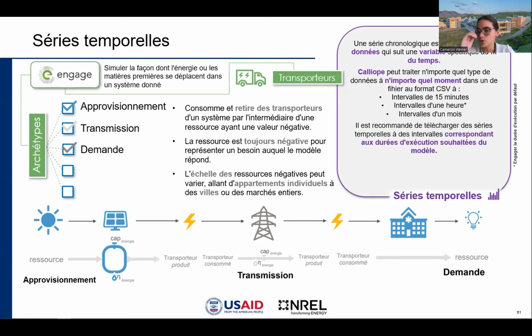We recommend that users upload time series data that matches that interval that you want to represent within your model. So if we want to run an hourly model, then we should probably upload time series that all have hourly time steps. This will really simplify things for you and make sure that you've got the right data in there and Engage is processing it correctly.